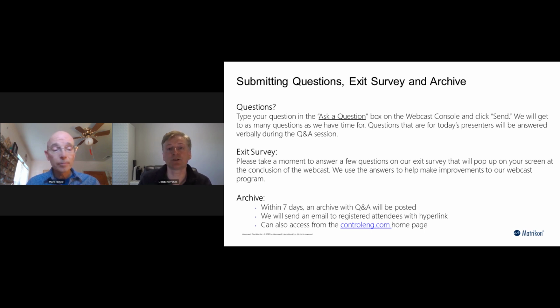And the question is, what is the rest of the market doing, or at least the part that's relevant to you? OPC UA provides a common base where there's a huge market penetration for what OPC UA does. It's well adapted to on-prem and remote communications, and it's just a question of which transport you want. So you'd have to look more, not just at which transport, but what overall system you want for the security, the modeling, the scalability. Both are very good, but there are a lot of factors to look at.